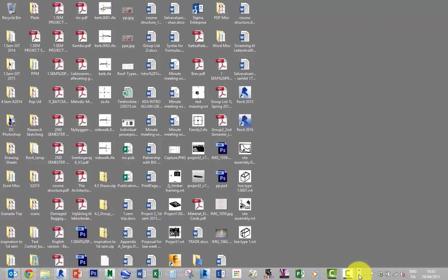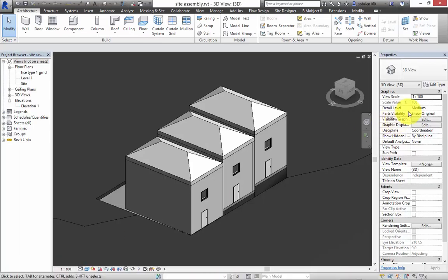If you have the, what they call the control line, what do they call it in Revit? Yeah, the core, exactly. If you have it on the inside face of the wall, then they will separate. If you have it on the outside face of the wall, the house will just get bigger internally. It depends on where you put the core line.